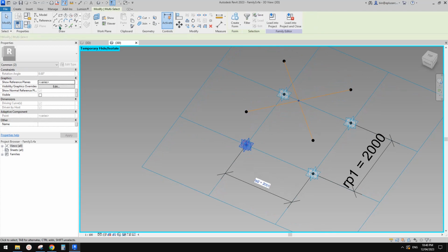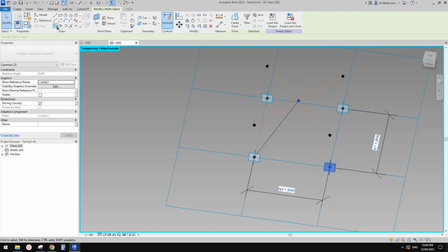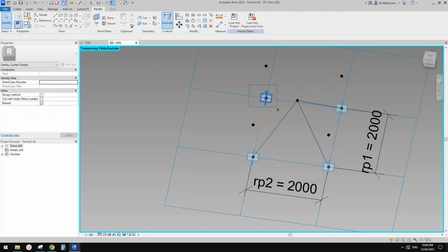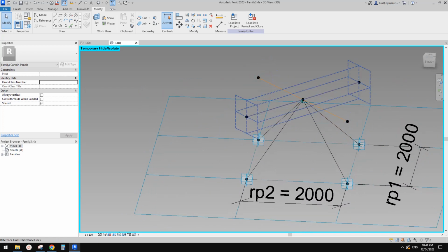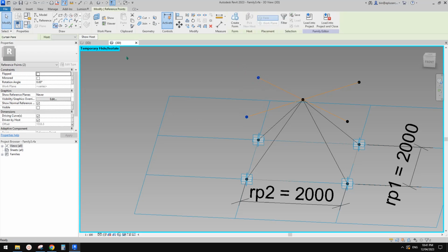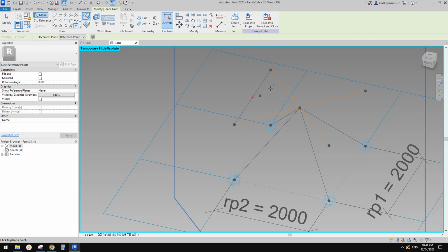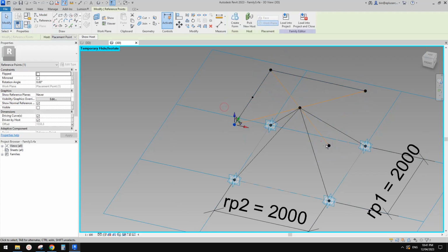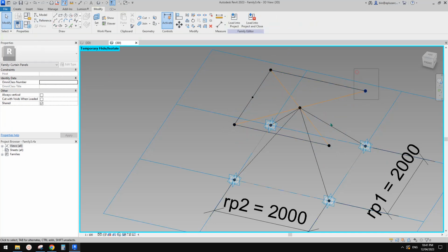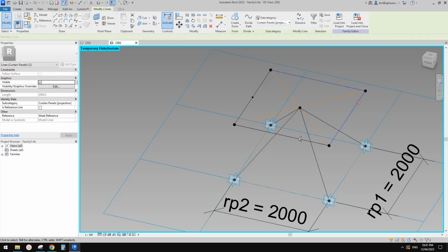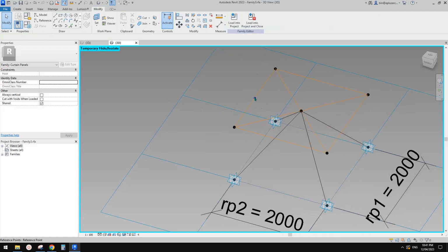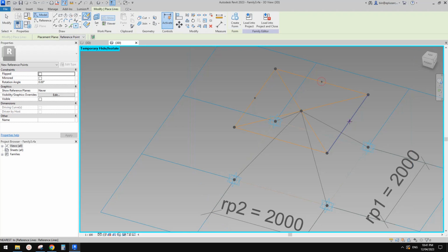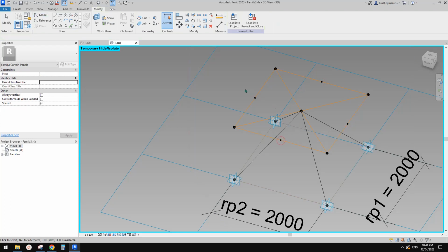Okay, so then we can connect this point to create those diagonal frames. And then, I think for this one, let me think. Yeah, I think we can probably, instead of offset from this point, just use these points and then place a midpoint. Okay, so let's just do this one, and this one, and this one. And once again, I want to check the reference line box and also change this to not a reference. And then when we have this point, let's place another 3, and then we can connect them.